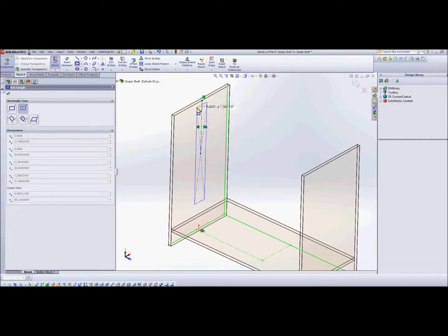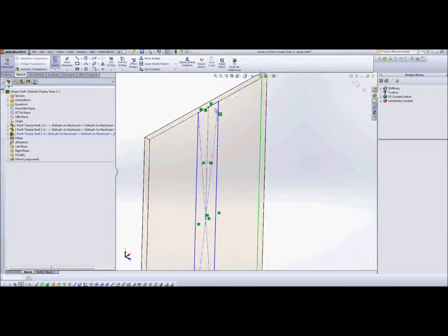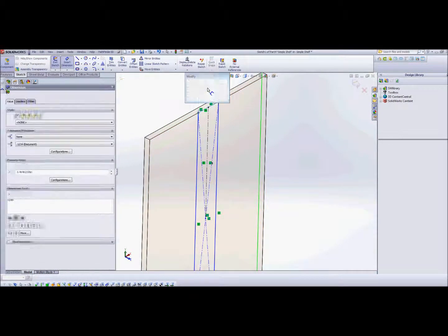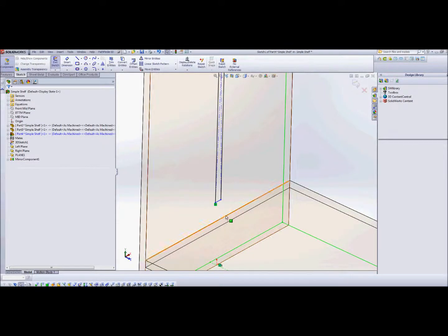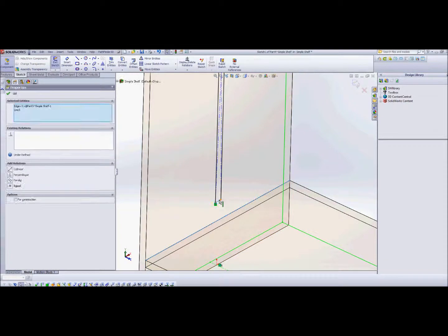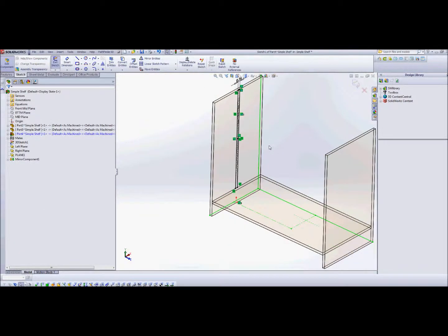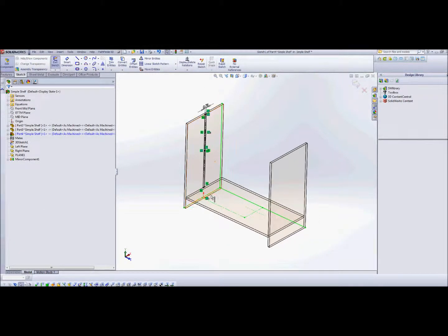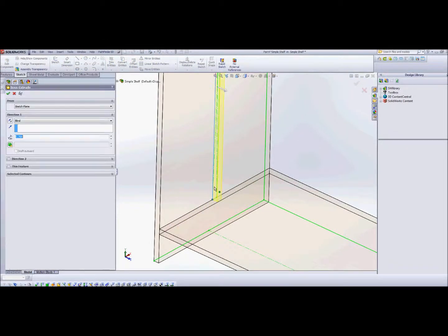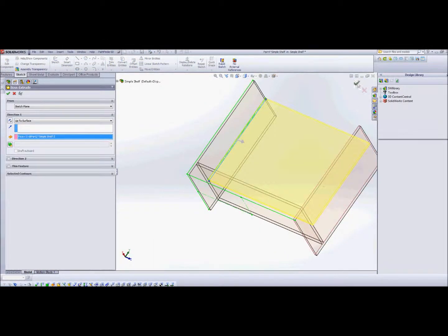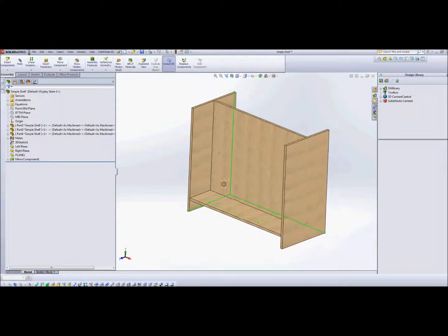There's a midpoint there, and then I'm using that to create this rectangle. And make this collinear. So now that will stay the correct size as well, and then I will extrude this over to the other side. So it's really easy.